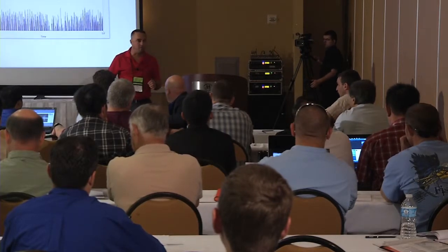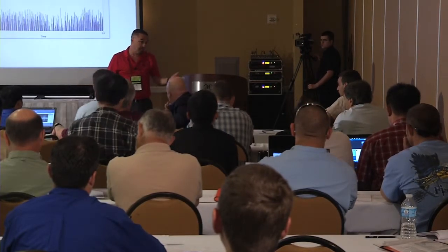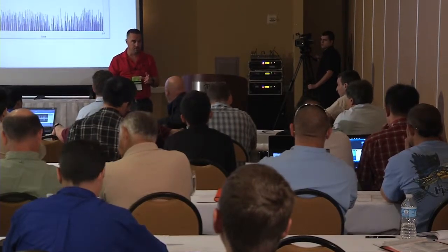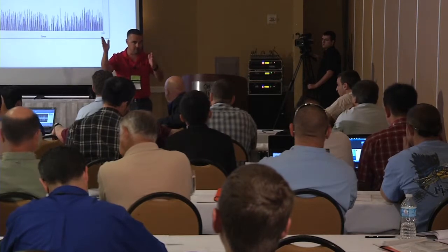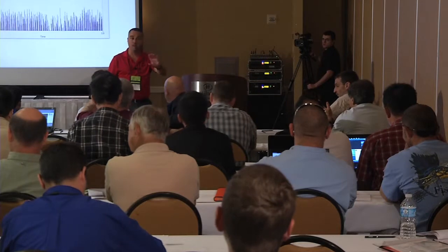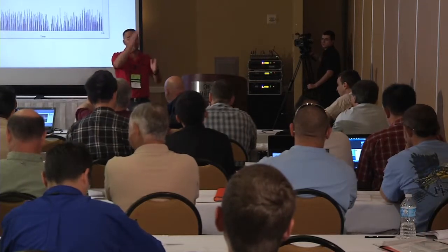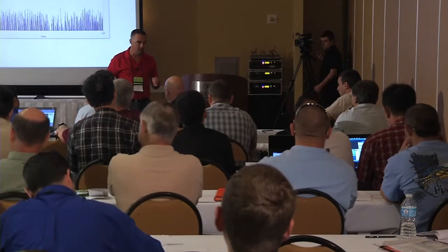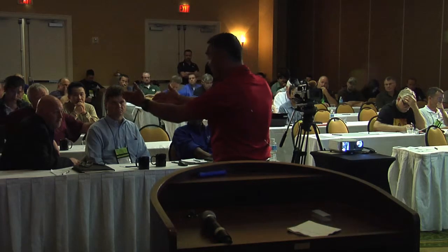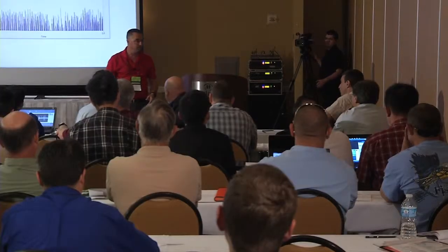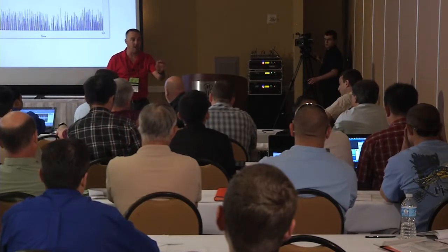Because remember, they're not going to be identical ever. Right, but the two signatures should exist in the comparison. A couple of 60 hertz peaks. The 60 hertz peaks should match up somewhere. No, they won't match. We're just going to have some number of fault frequencies peak on the 60 hertz harmonic. They might be at the end of the spectrum, they might be toward the beginning. There may be one or two on one, and the overlay may have four. You're talking about similarities. Similarities, yeah, not identical,